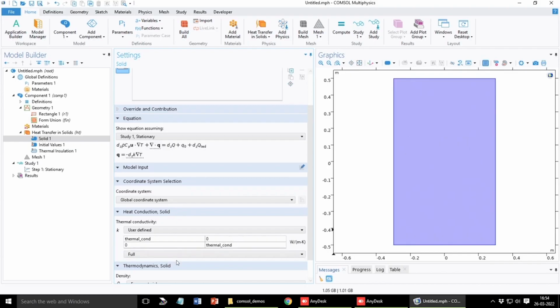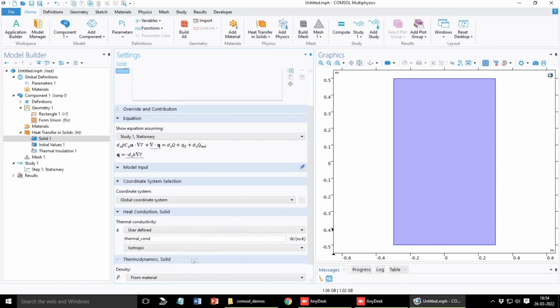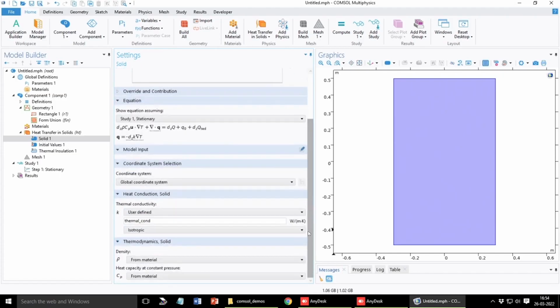and you can define all the anisotropic conditions of this. Okay. So, for the sake of simplicity let us write this to be only isotropic in this system, and we consider it to be constant, but very easily you can write that to be of any other type of functionality which you want. For example, most resistances that you see have a very strong function of temperature. So, you can write thermal conductivity as a function of temperature too. Semiconductor materials are highly dependent on temperature.